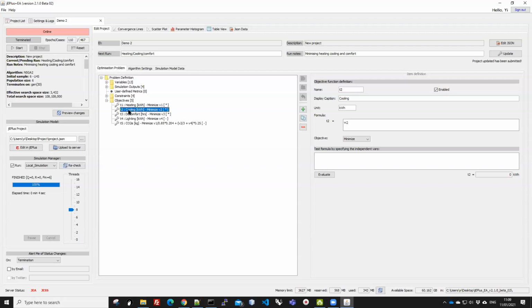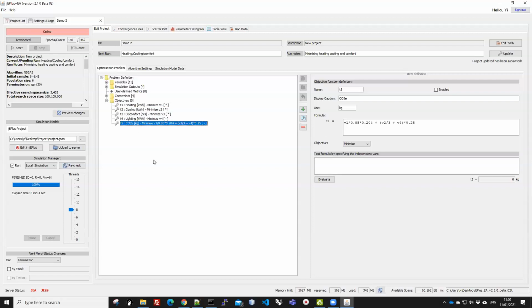If it comes from gas and electricity, the best way is probably to calculate the operational carbon emission, something like that. So if it is gas heating, it is divided by the efficiency of the boiler and multiplied by the carbon factor of your gas supply. So this will give you your gas emission per kilowatt hour.